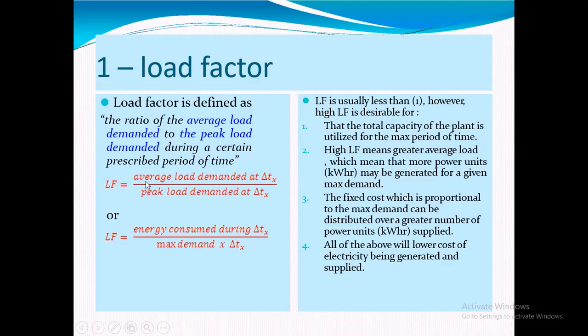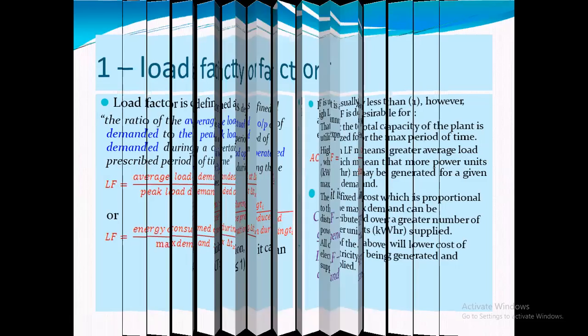That load can be expressed in energy, because household energy is consumed in kilowatt hour, and it is a unit of energy. Our bill or consumption of load is charged by the utility in kilowatt hour. That's the reason the formula of load factor can be written this way: energy consumed over maximum demand. This is the main formula of load factor. If anyone has any query, please feel free to ask. Then we go towards the next slide.